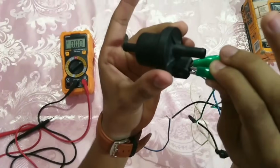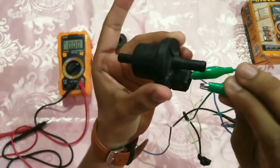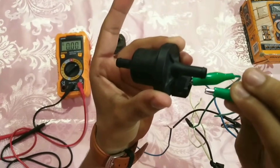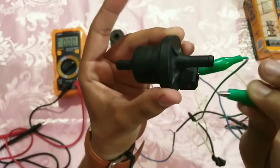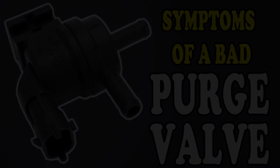You can test the valve by applying direct 12-volt power to it. A healthy valve will produce an audible clicking sound as it opens and closes when power is applied and removed. We previously explained all EVAP purge valve failure symptoms in a dedicated video. Link in the description below.